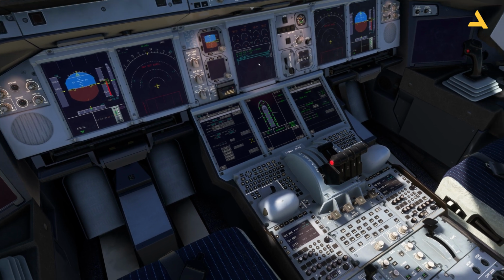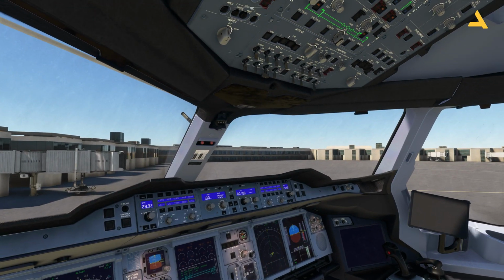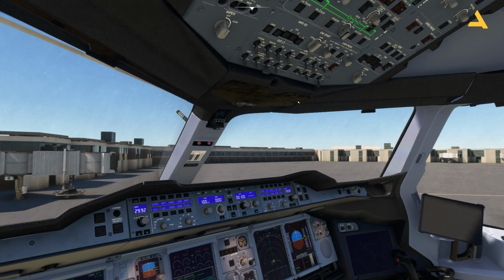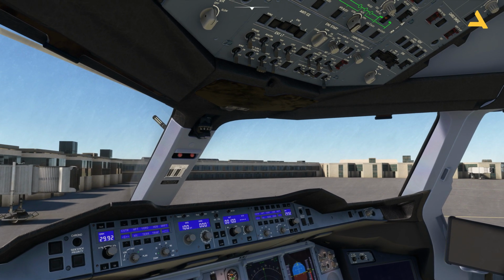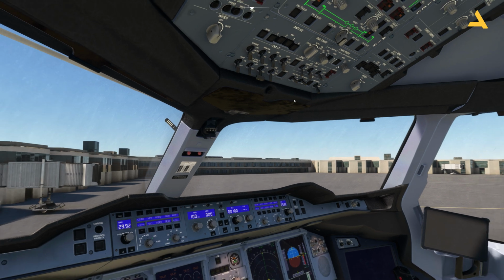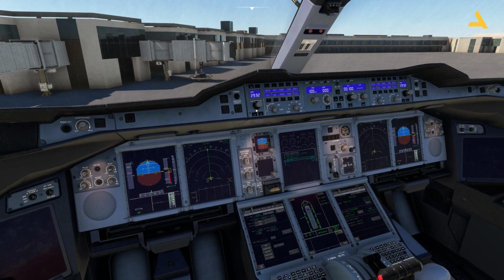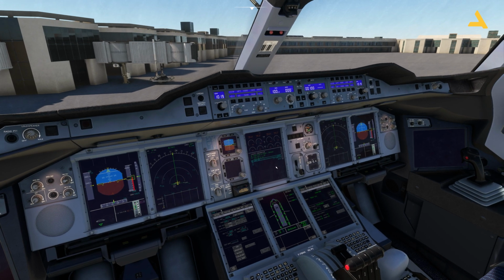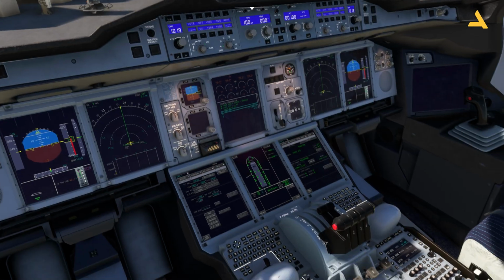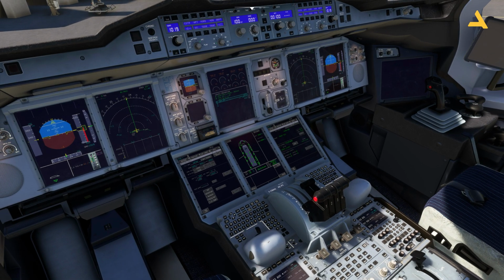Seatbelt signs on. So as the fueling is done, I can turn on the seatbelt sign. I can turn on the no mobile sign. And plus I can arm the emergency exit lights. And plus it also says baro reference. So I can change the units over here and press B in order to get the barometric pressure, which is there. So now this step is also complete. And then I can press this tick twice to complete the checklist.